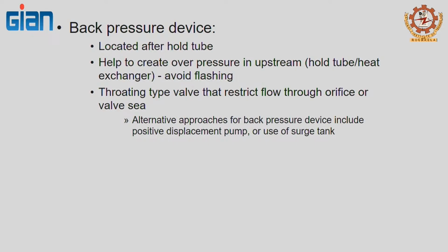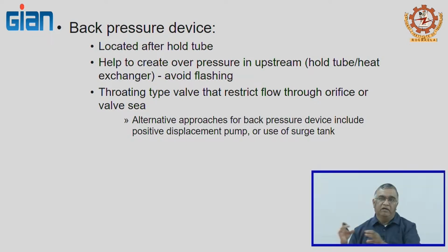Now, I talked about the aseptic processing temperature being 130 to 140 Celsius. If you remember, water becomes steam, it boils at 100 Celsius, whereas your product here is being processed at 130 or 140 C. So how do I maintain the product in the liquid state in my holding tube?